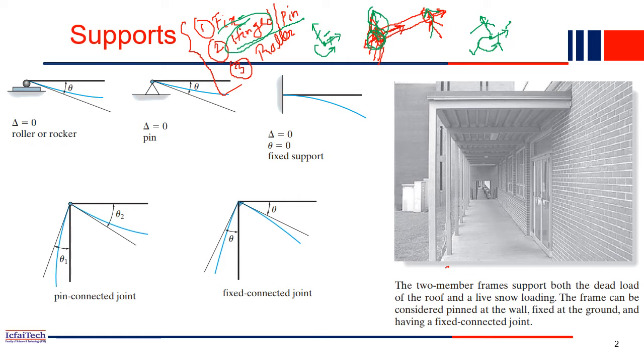Has a hinge joint. So in many places you will find hinge joint. Hinge joint means the joint translation is prohibited. Like this joint cannot move in the horizontal direction, cannot move in the vertical direction. These two are not allowed, but this joint can rotate. So that is our second joint, the hinge joint.